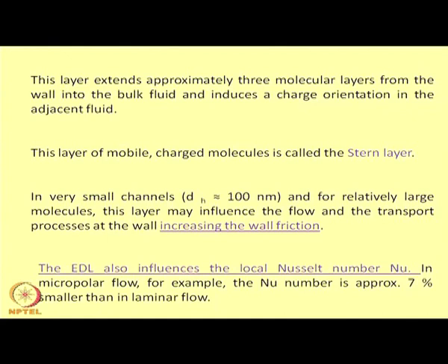So, it not only changes the wall friction, since the velocity near the wall for such cases would be smaller, and therefore the convection is going to be smaller, and if the convection is smaller, then the value of Nusselt number will turn out to be smaller as well. So, for micropolar flow, the Nusselt number could be about 10% smaller in laminar flow when there is no EDL. So, the EDL influences the flow and heat transfer for flow